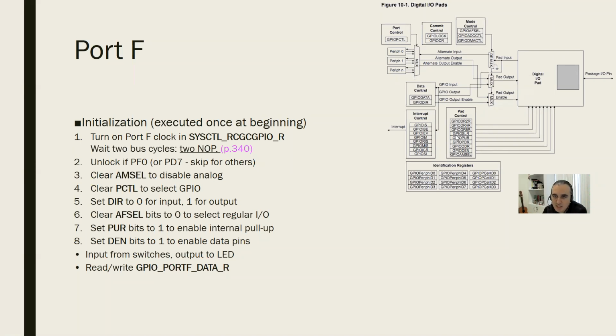I mean, this is a register, and if you want to change a flip-flop's value, in Barbarossa's course, you'll remember that a clock needs to be fed to the flip-flop so that any value could change. And actually, these control registers are a bunch of flip-flops or similarly designed digital circuitries. So in order to be able to do anything, we should first feed clock to the device.